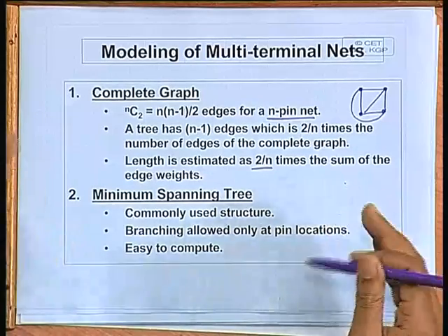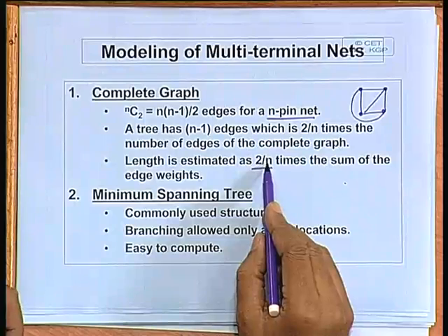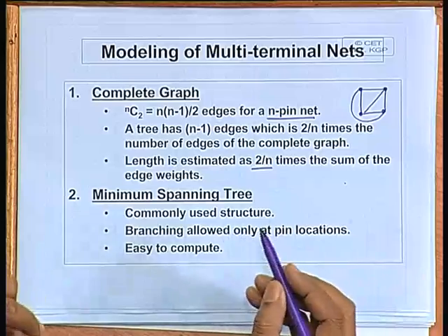The cost which you get is the actual cost, because the spanning tree is a structure which is close to reality. So you do not have to multiply it with any weighting factor finally. Yes, when you said you will find the sum of edge lengths, for one particular edge we will find the distance, like straight line distance. We will take an example. These distances are all computed as Manhattan distances, not straight line distances.